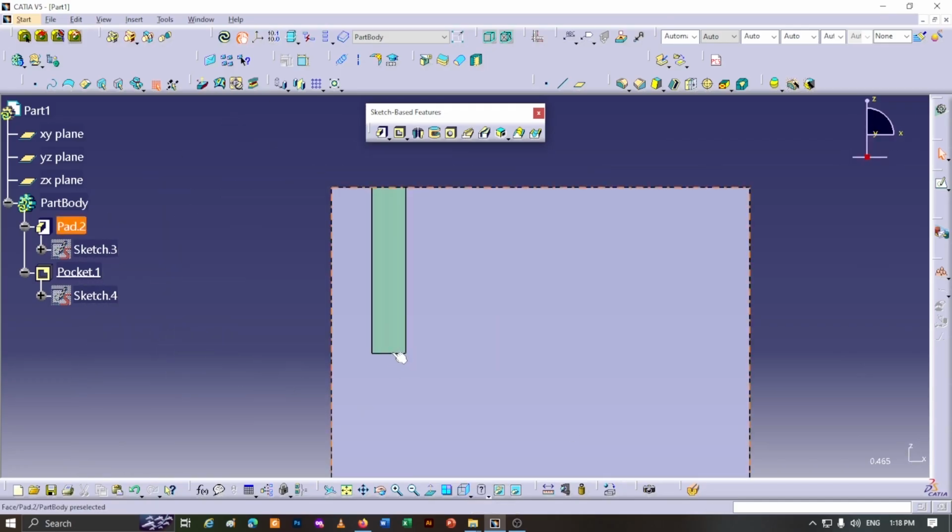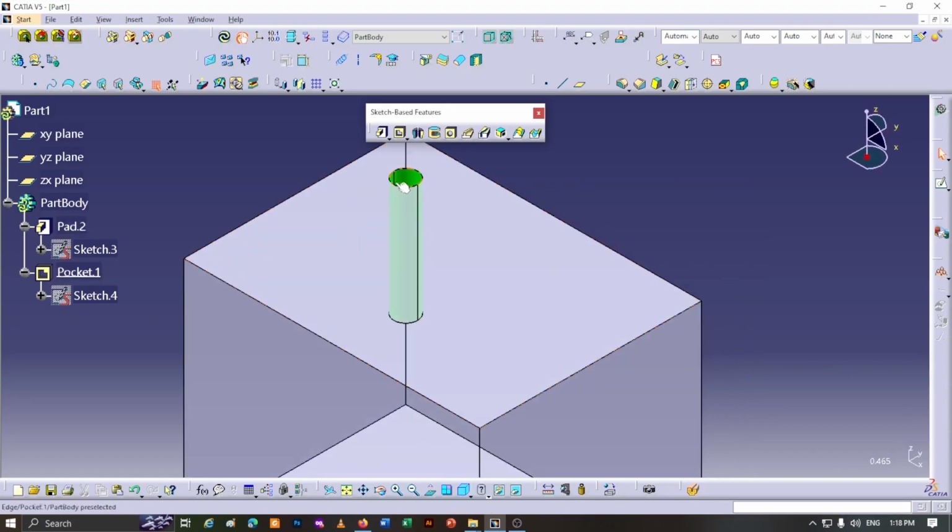The bottom of the hole is flat and does not have a conical shape. The upper edge of the hole is simple. Its size and location can be changed. The hole diameter must be entered manually. The hole does not have threads. To thread it, we must do it later with another tool. But for our convenience, the software has provided another tool called Hole.